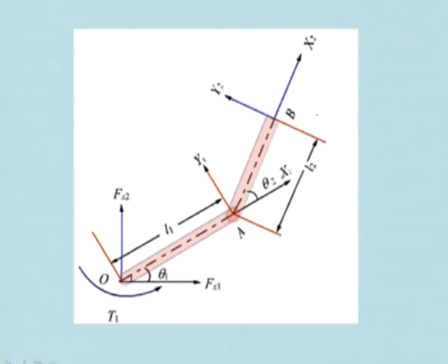We could have drawn the free body diagram of only ring 1, but in that case the joint reactions would come at joint A. Those are unknown to us, so we do not want to find them. That is why we are doing it like this, showing the joint reactions fx1 and fx2 here, and the torque T1 is acting.